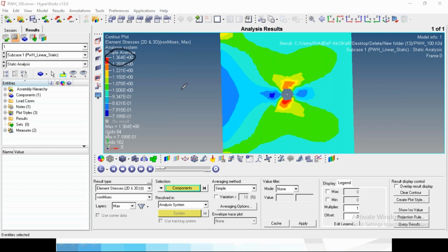As well as with that value of maximum stresses, you can see that the distribution of the stress has also changed. So this stress distribution is more accurate, you can say, as compared to the previous one. It is not the exact output we want, but it is better than the previous one. So now in the same way, we'll select a smaller element size. Let's go to 10.